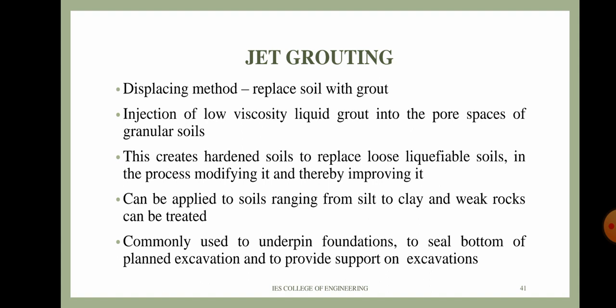Here we are injecting a low viscosity liquid grout into the pore spaces of granular soils, and this injected grout creates hardened soil to replace soil which is loose and liquefiable, in the process modifying and thereby improving the soil condition. Jet grouting can be applied to soils ranging from silt to clay, and rocks can be treated. That is, it is applicable in different conditions. Jet grouting is commonly used to underpin foundations, to seal the bottom of excavations, and to provide support on excavations.